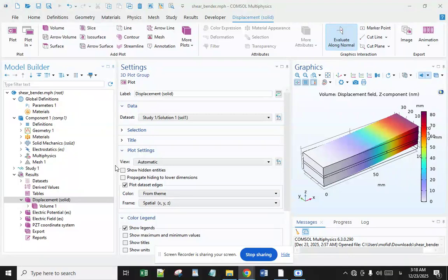Comparisons between both actuation mechanisms in the static piezoelectric actuation show that only thin extension actuators are efficient. Shear actuators, in contrast, are more effective for a medium thickness range. It was also shown that a shear actuator's performance is less dependent on a structure's stiffness. Moreover, for rigid structures, the shear actuation mechanism presents better performance than the extension one.